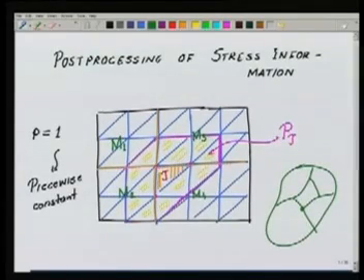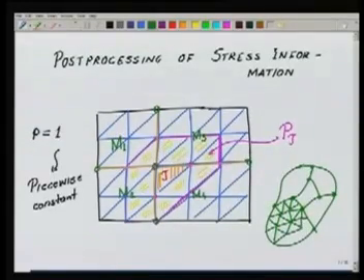And at the point of intersection of the material domain with the domain boundary, or between two material domains, for example here, at these points you have to have a node. So when you make the mesh, ensure that these points are nodes. Then only you can go ahead and make the rest of the mesh. For example, I am making it in this piece here. This should be very clear, otherwise your finite element solution will be very far from the actual solution to the problem. So this way we could complete the mesh in this part, and we continue the same thing in the other region. This is one more thing that you have to keep in mind when you are doing the finite element approximation, because nobody tells you that the material will always be of the same type. You could have different types of materials.